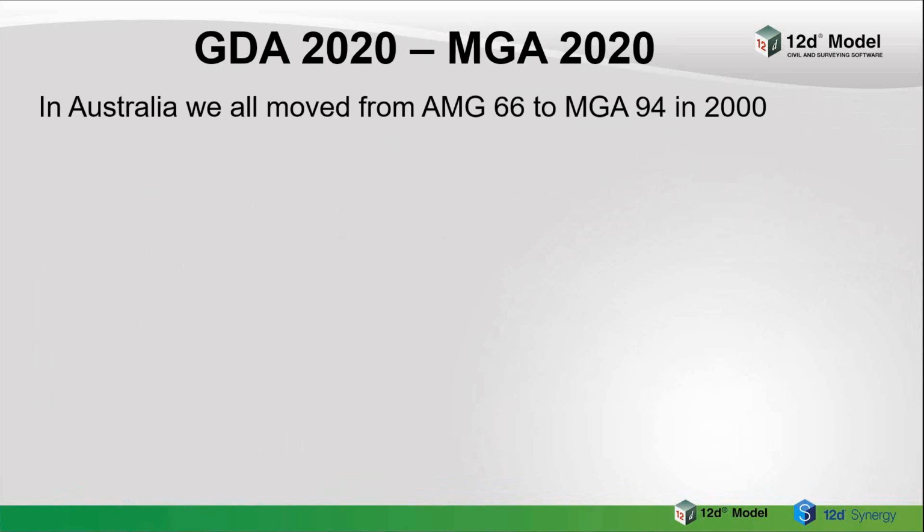Another thing we have to be aware of in Australia is GDA 2020 or MGA 2020. GDA is the model of the Earth, MGA is our coordinate system. Back around the year 2000 we moved from AMG 66 to MGA 94. That was a big change. So we're all pretty well using MGA coordinates. These things are northings now here in Australia.